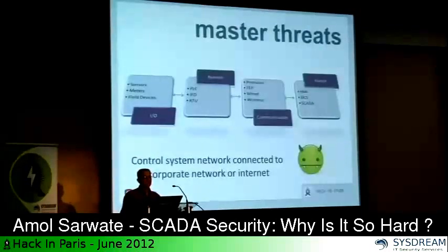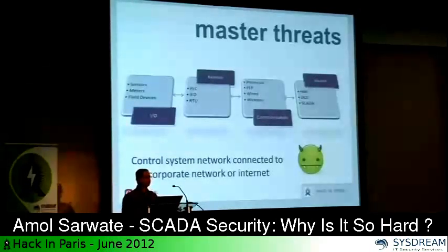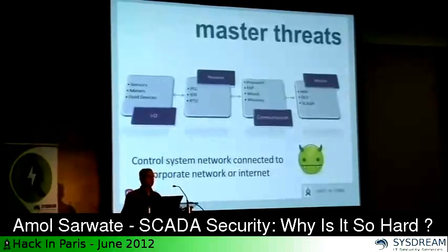So lastly, we focused attention on this last component. This is the control component, where, as I mentioned, there are operators manned 24/7 in a manufacturing plant or in any sort of plant to look at what's happening in the system. And the number one threat that we found in this area is that the control system network is connected to the corporate network or sometimes even to the internet.